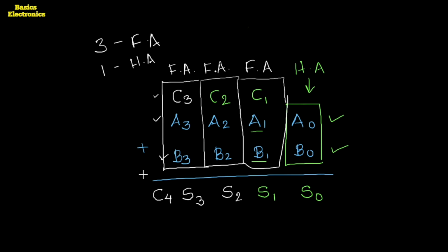What if instead of this half adder we use the full adder? To make a common hardware we can use four numbers of the full adder, so the hardware gets common. But we have to make one arrangement. The full adder has three input terminals, as it performs the addition of three binary bits.